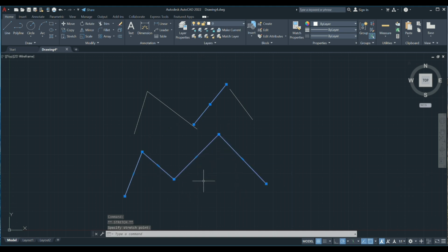So how can you make this shape like this shape? Before we begin, let me just tell you the benefits of using a polyline. First, it's just easier to work on a shape when it's connected all together. And of course, if you want to disconnect a line from the shape, you can always do that, and we'll talk about that later. And second of all, let's just say you want to give your shape a color or a line weight or just some texture. You just click on one line and the whole shape is connected, not like picking each individual line.